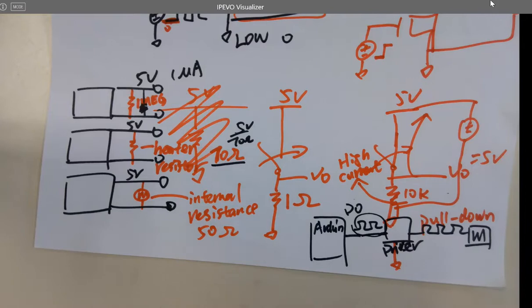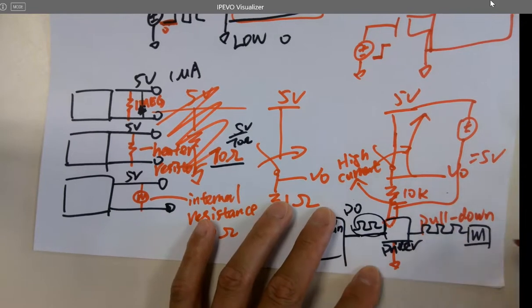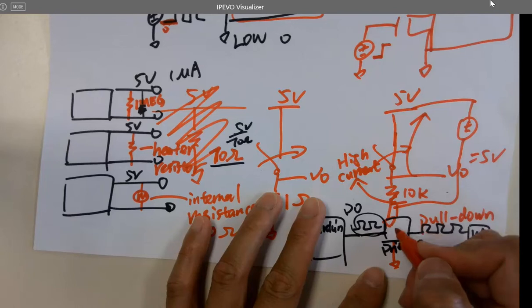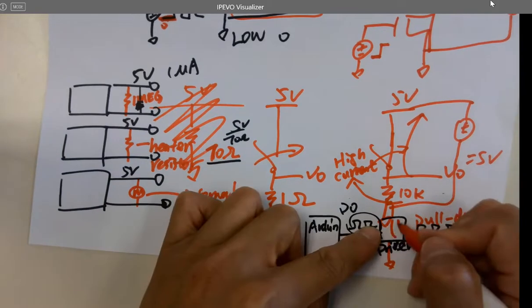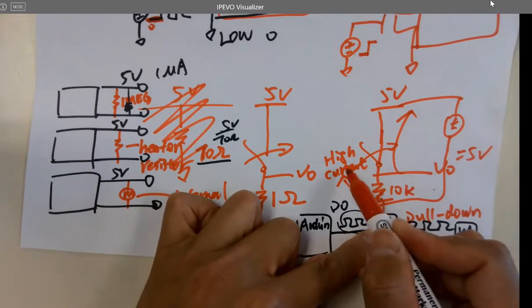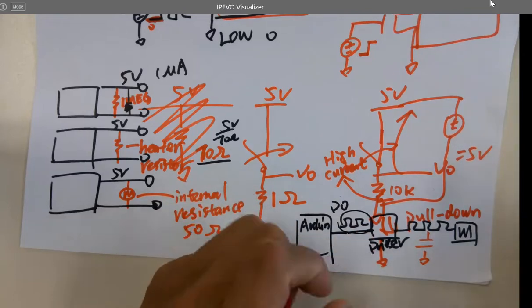Why is it adding current to it? No, it's not amplifying it. It's the same 5 volts logic. It just has connections to the power source and ground, because all these driver devices have them. So it has a pathway to source more current from a high current power supply. You know what I mean? Whenever I turn on the device, it is able to source a lot of current from the high current power supply to fill up the cap. The loads are capacitive, resistive, whatever, right?